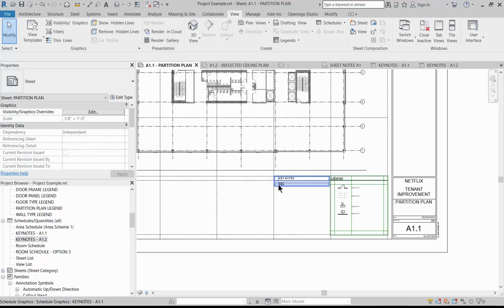And you'll probably also have sheet notes on your schedule sheets, so on the door schedules, and you might have them also on the partition type schedules and even the finish schedule, if they're not already covered on a finish sheet. So not the enlargement elevations, but the other sheets. And there is nothing particularly sophisticated about those. What you do is you just create a drafting view.